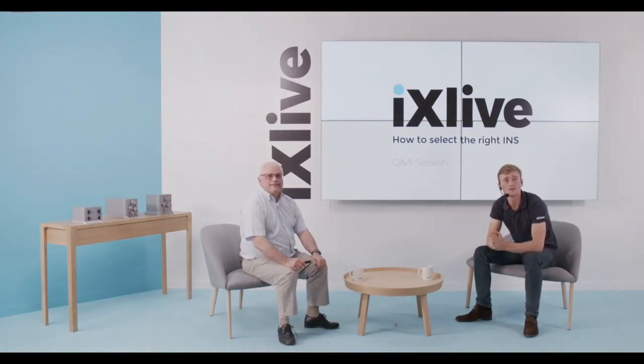So next one, I don't know this word. Does the gunman filter differ in different zones? Gunman filter, you know? Kalman filter, maybe? Differ in different zones. No, the Kalman filter itself, I'm not sure I understand well the question, but the Kalman filter itself does not depend on zones. Maybe on the pole. On the pole, it's different. Well, no, even on the pole, it knows that it's close to the pole, so the computations, providing that you took care of every detail in the math, it would work anywhere.